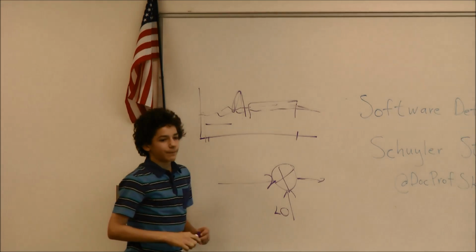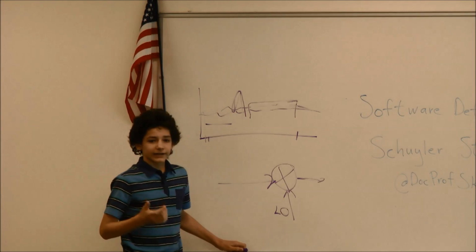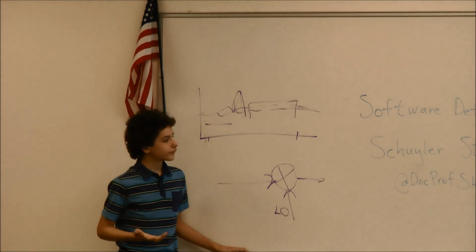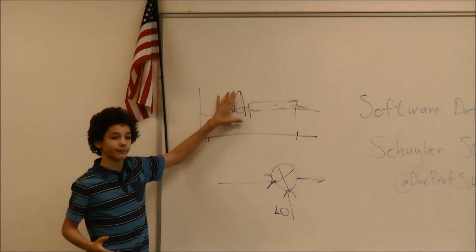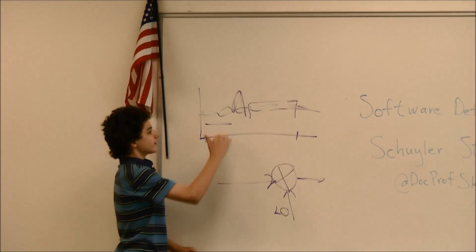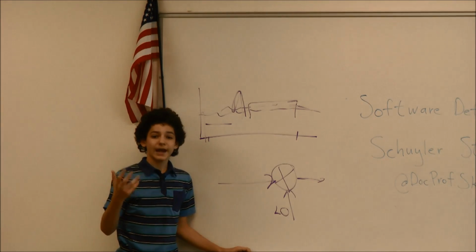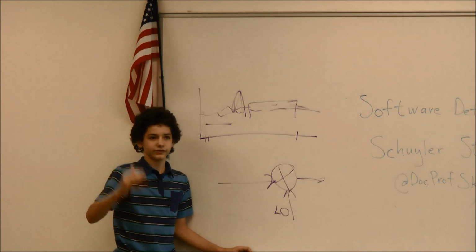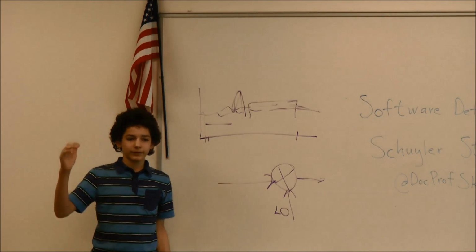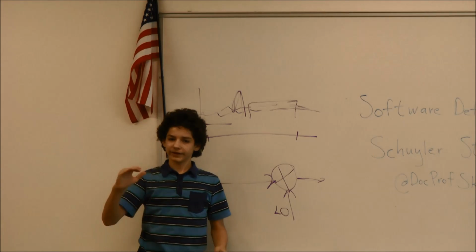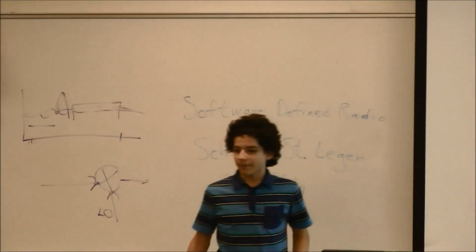What can happen is, depending on the architecture of your Wi-Fi card, and this is actually a big problem for cell towers, if you have a close client and a far client, or in this case a microwave generating noise, this will cause issues with the amplifier, and it might peak or clip, or it could damage the ADC if the voltage gets too high. So this can be another problem where your router needs to turn down the gain, but then it can't receive the signal. So now we're going to do some actual demos.